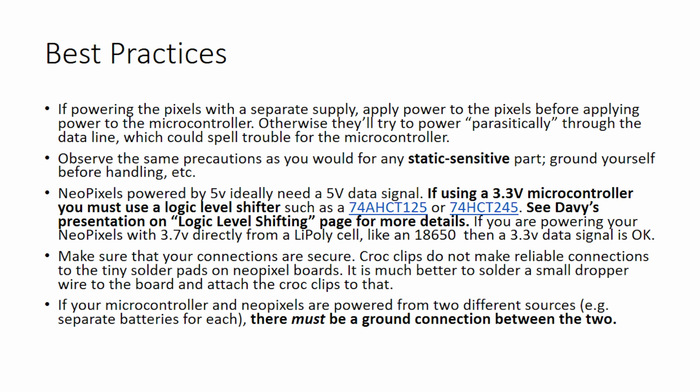In fact, it's best practice for every microcontroller, irrespective of what you're doing with it. It's good practice that when it comes on, to make all of the pins inputs. Because if you put an output on as the micro comes up, something's going to happen. Whatever that output's driving is going to actuate. And you don't want things actuating when the microcontroller's not in control. So it's good practice. Actually, most Atmels and PICs, when you switch them on, they do come up as inputs until you declare them as being outputs.